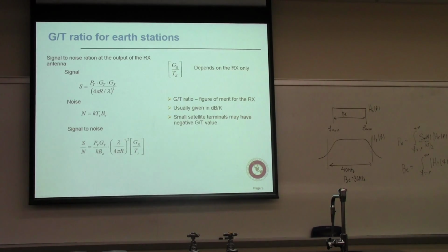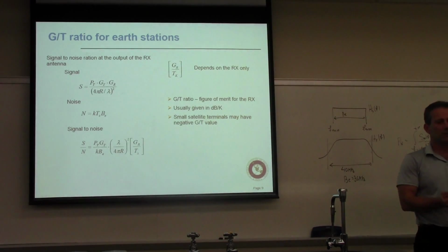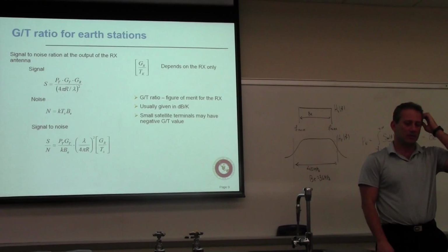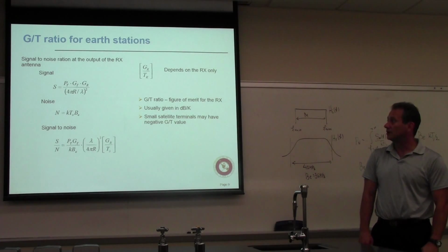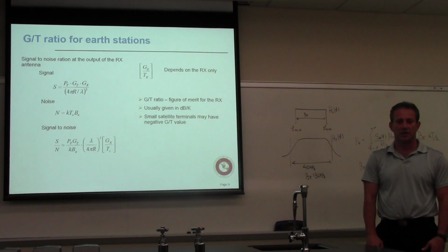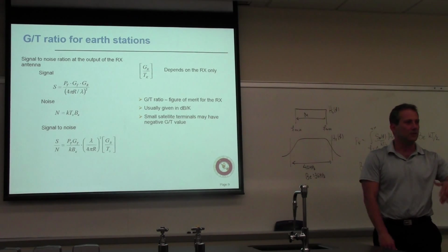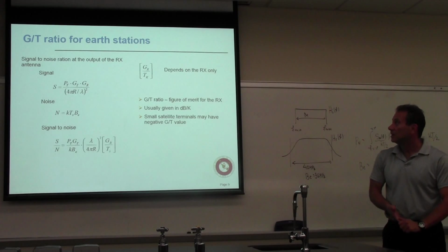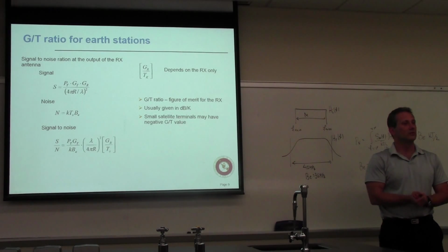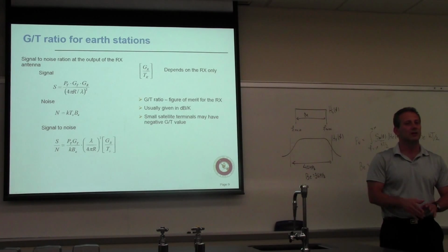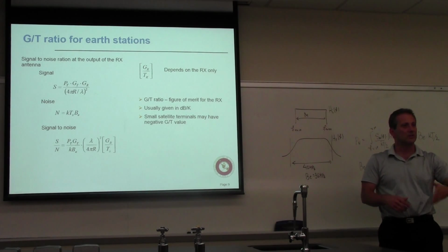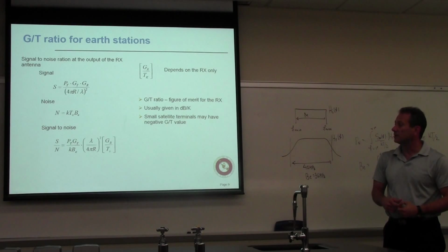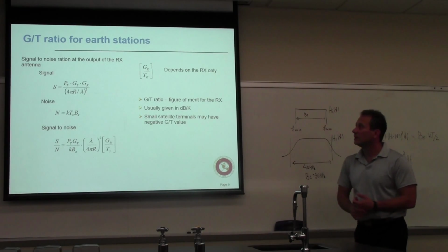Okay. In satellite communications, a lot of times we talk about the G to T ratio. They would talk about G to T characteristics of whatever receiver you're trying to characterize, and you would say this system has a G to T of, let's say, 10 dB, 20 dB, or whatever may be the case. Now, this is kind of an equivalent of the signal-to-noise ratio, right? That we're familiar with in the terrestrial world, but because your temperature varies here, that's why we prefer to express it in this way in satellite communication.